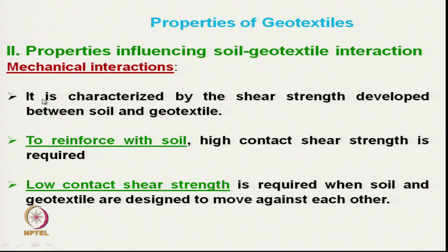This is very important as far as reinforcement application is concerned. To reinforce the soil, high contact shear strength is required. So, depending on the contact shear strength we can use it for reinforcement.